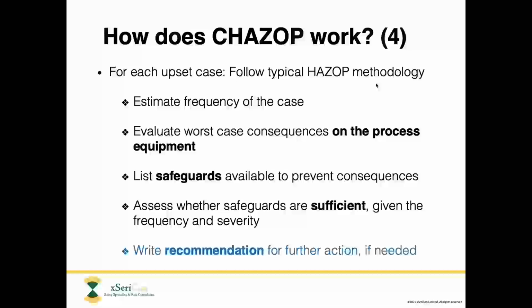And then here's a couple of examples of yes/no questions. The first one relating to security. Is there a way to prevent unauthorized access to the control system cabinets? Second one, has a cybersecurity assessment been performed? So that is quite a wide-ranging question, but really that's just a prompt to confirm that a separate assessment has been done for this scope, the functional area that we're discussing.